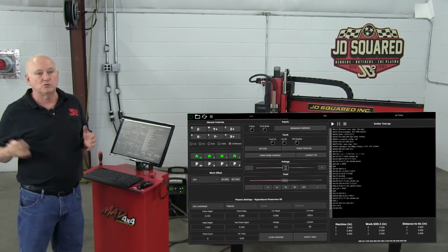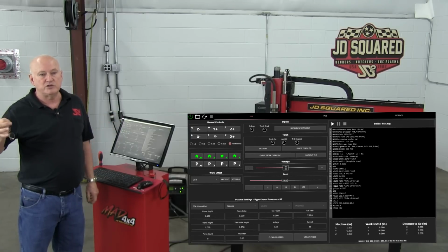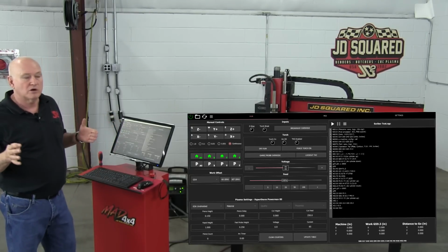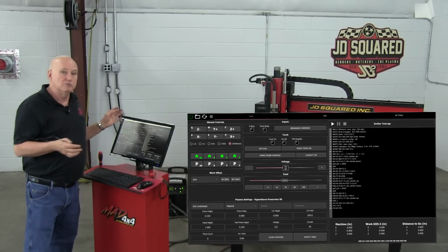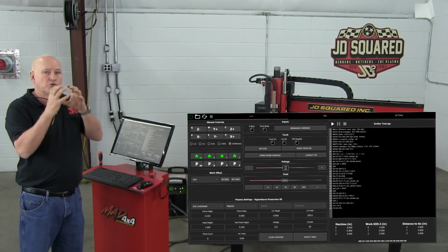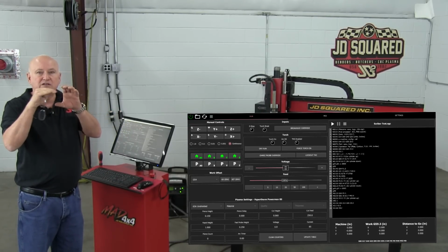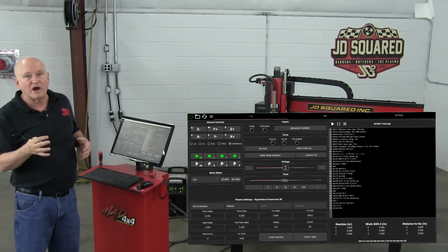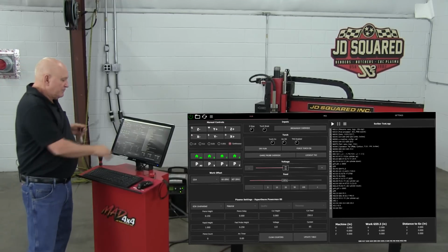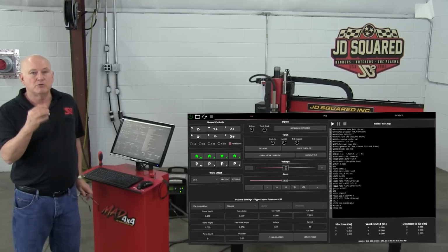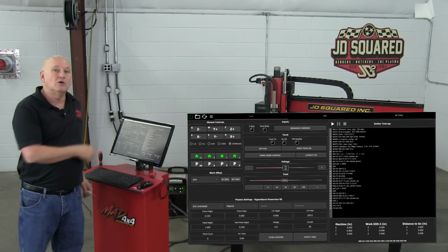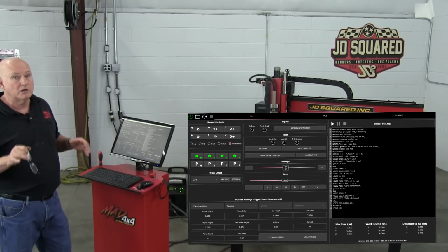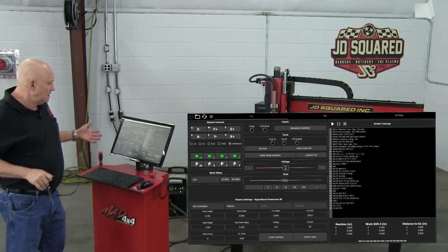This is why, for instance, we're not really a fan of setting a default tool table in Sheet Cam. The way it works is if you were going to pick 45 amp consumables for mild steel, that's another group in Sheet Cam, because it looks at different tools as different metal thicknesses and different kerf widths. So the bottom line is, if you update a table here, remember that you're going to need to update the table in Sheet Cam. It's an easy process. There'll be a video on it. It's no big deal, but remember that it is critical.